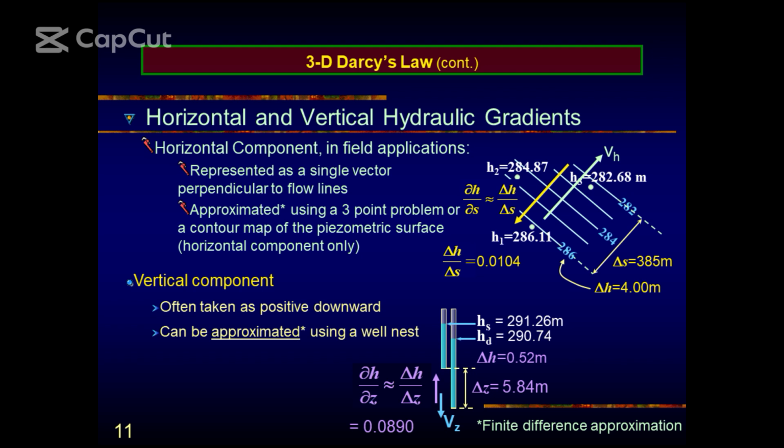No, I'm not referring to elevation contours. I just made reference to elevation contours to explain the fact that at every point on the contour, the elevation is the same. For equipotential surface or contours, at every point on the contour, the pressure head or piezometric head is the same. Do you get the point?